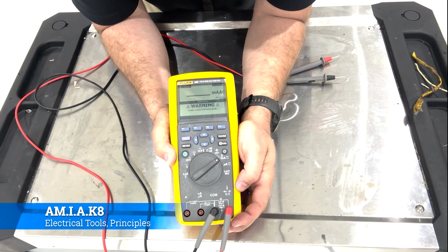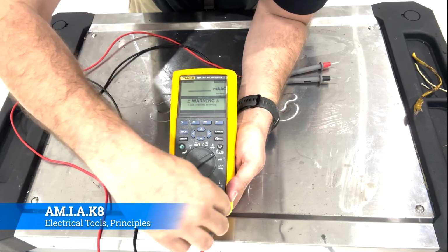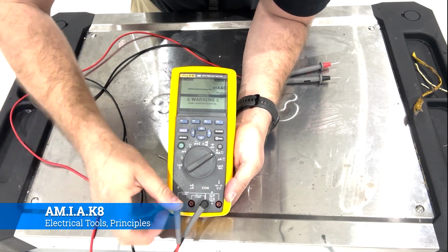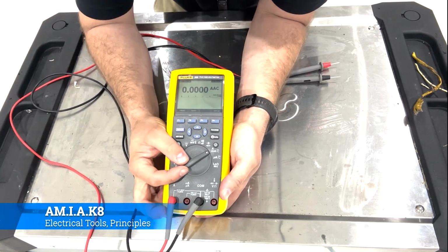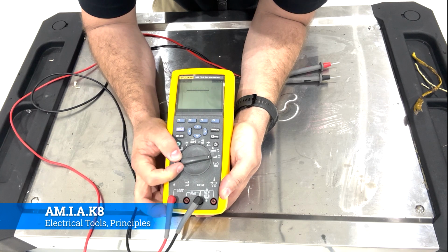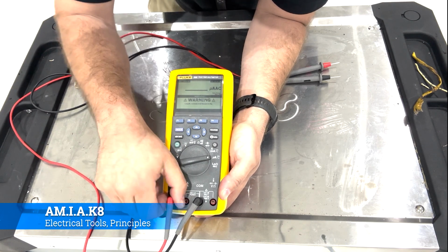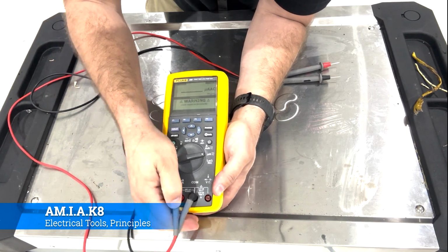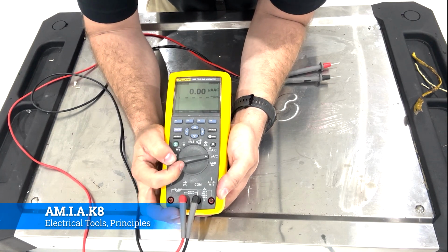And then now we're into amperage. And you notice it's giving me a warning. That means that we have to move the lead over to the fuse side, so that in case the meter were to be exposed to a high amperage, it wouldn't destroy the meter, it would just blow the internal fuse. Each one of these is fused differently, so you'll notice that as I change the dial, I also have to move the lead to the appropriate input there at the bottom. But the common always stays the same.